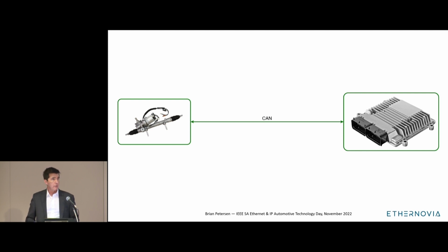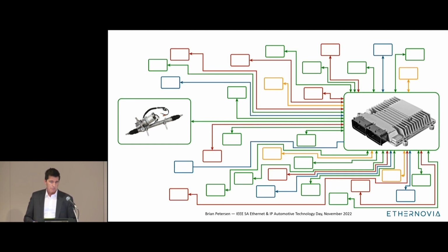Now, this is great, this is obvious, but this drawing is also rather misleading because in an actual vehicle, an ECU may have a dozen or more interfaces communicating with a wide variety of sensors and servos and other ECUs. And of course, CAN has been joined by LIN and MOST and FlexRay and I2C and A2B and, of course, Ethernet. And so even though we've made progress by replacing analog wires with a digital wire, the ever-increasing proliferation of these various sensors, servos, and ECUs has not resulted in a reduction in complexity. All we've done is kicked the can down the road.